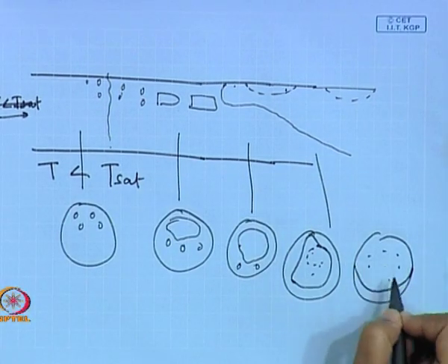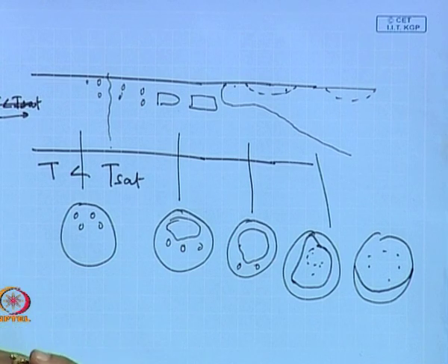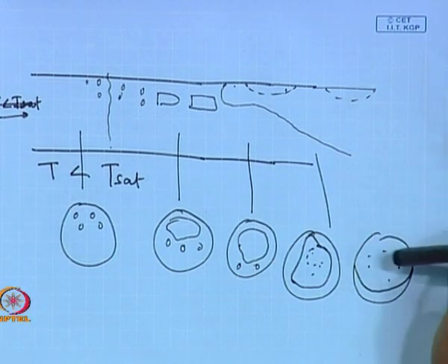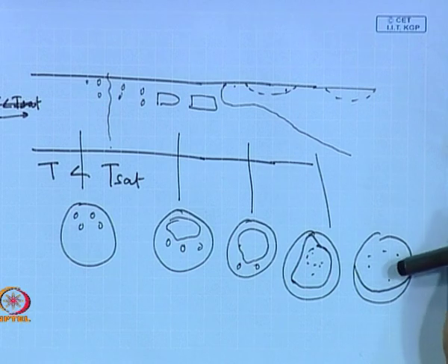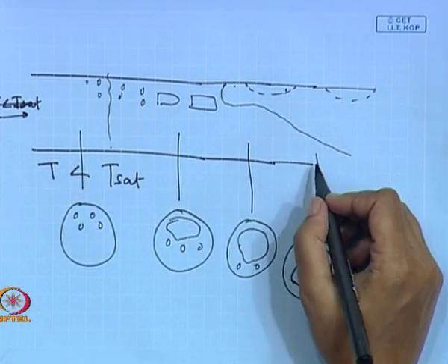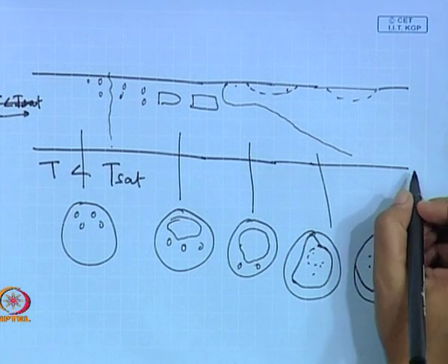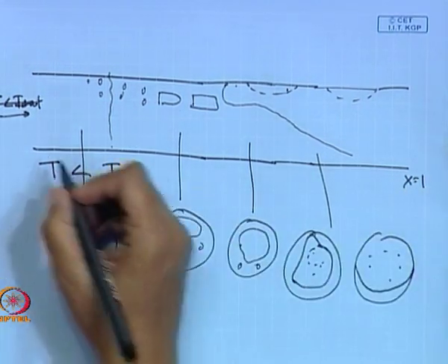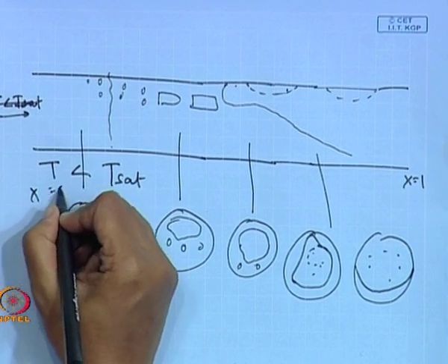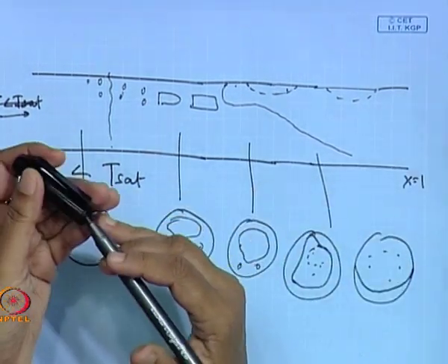So, therefore, this constant intermittent drying out and re-wetting, this is something very unique. And finally, after that, of course, just like the vertical heated tube, here we have the quality equal to 1, here we have x equal to 0, here we have only vapor flow. Okay.